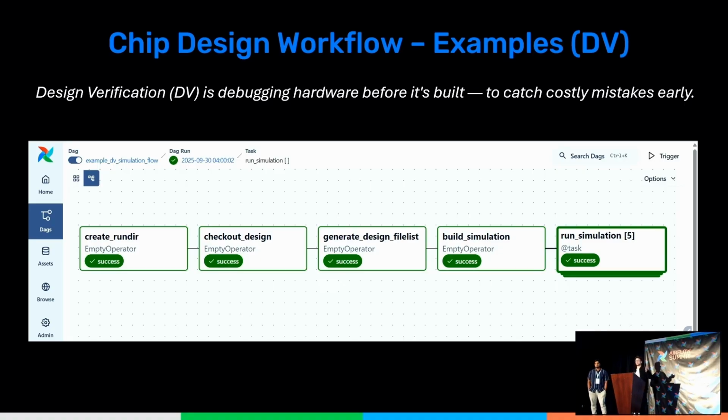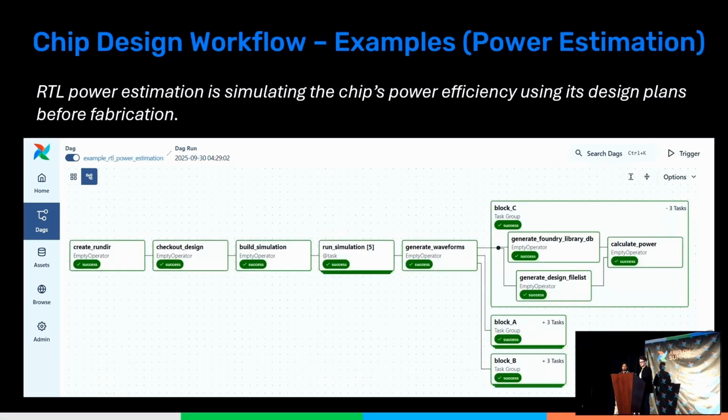Generally, a file list is ingested by a simulator to compile your design, make sure it elaborates and synthesizes cleanly, and then actually run the simulation. You work your design through different pieces of behavioral context and qualify the results to see if your design actually works.